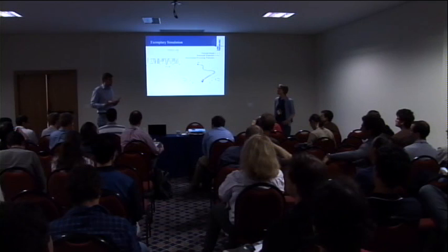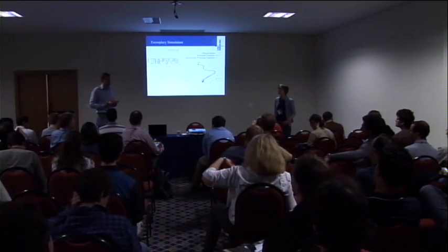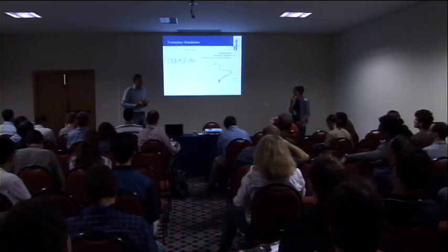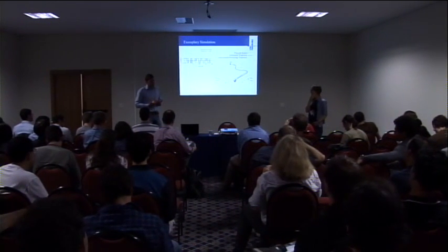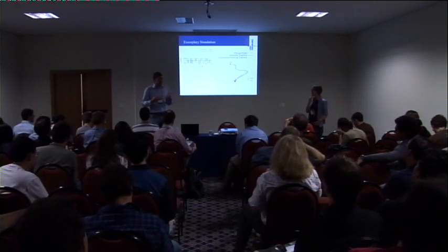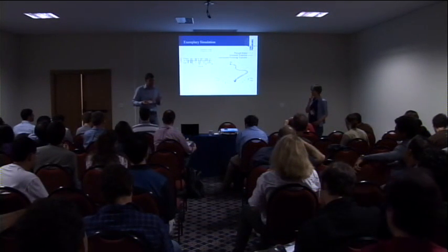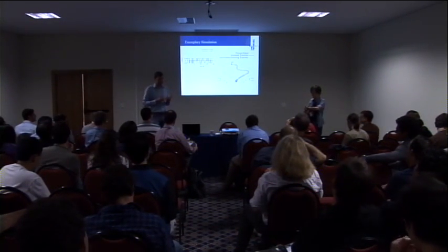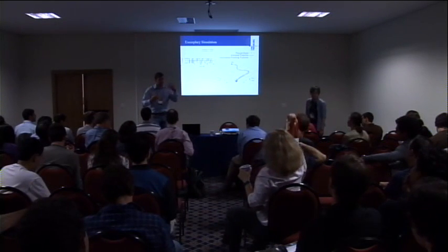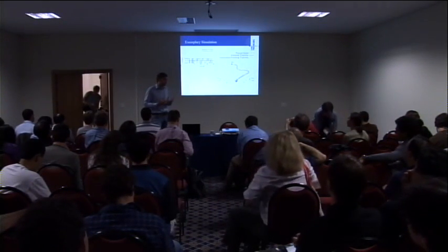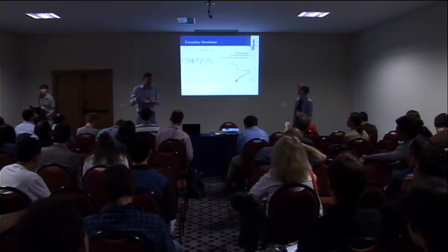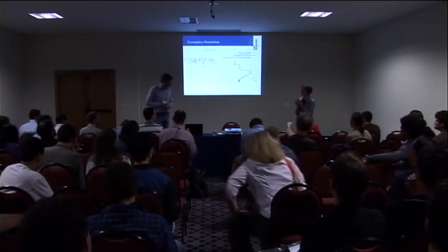I think, of course, normal or classical control approaches are much faster, for instance. This is one thing. Model predictive control is faster currently. I think the interesting thing here is that we can process some unusual behavior of the system. For instance, if we have a control signal where we want to make sure that we have a logical consistency, for instance, if we have to preheat a thruster before we can activate this thruster, we can do that directly with this approach. So this is an advantage, but of course it's difficult to compare this approach directly to classical control approaches. Okay, I have to stop there. Thank you very much.